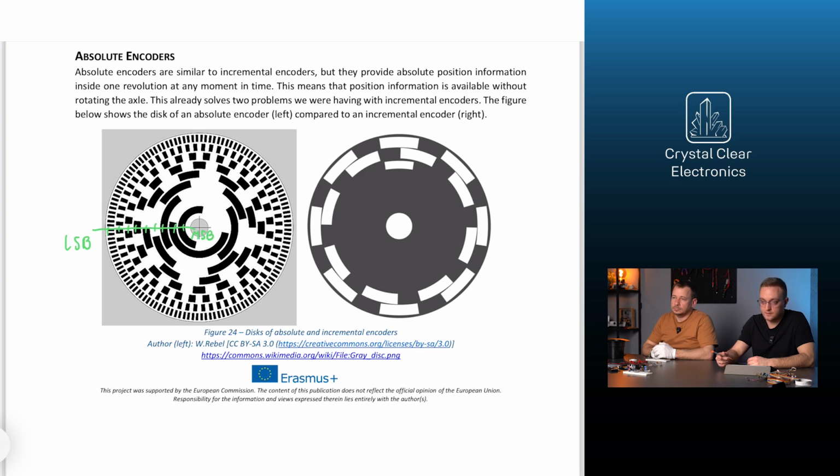Since we are not talking about only counting pulses and increasing a counter, but detecting absolute position information, interfacing the sensor is not that easy. We are not talking about transmitting impulses, but transmitting, in this case, 9-bit numbers. To do this, we usually need some kind of high-speed serial communication. Most modern robots, for example, use absolute encoders to detect joint position.